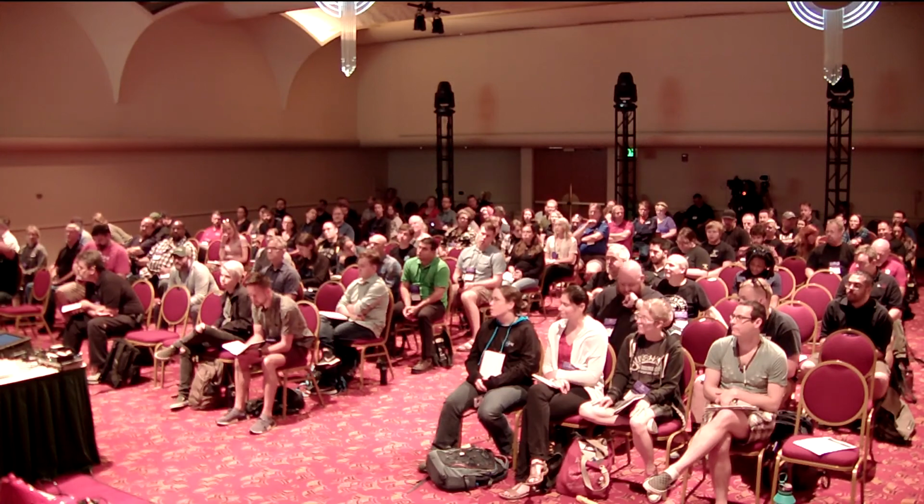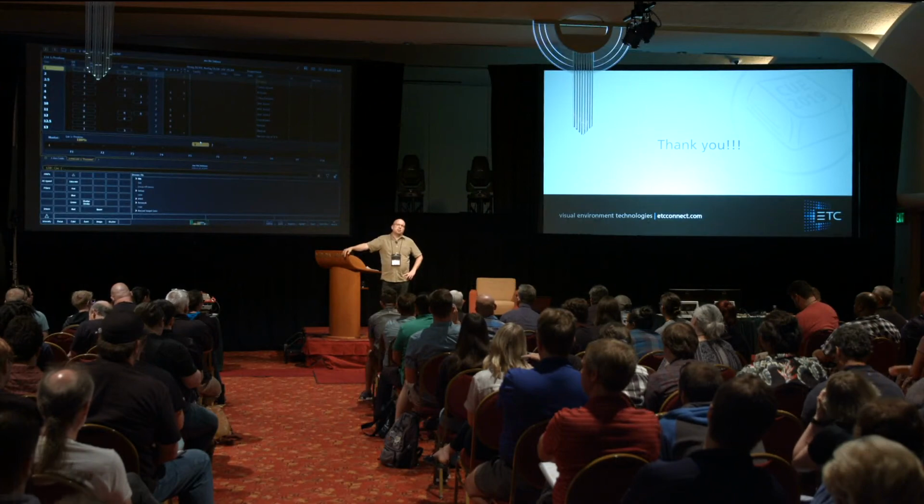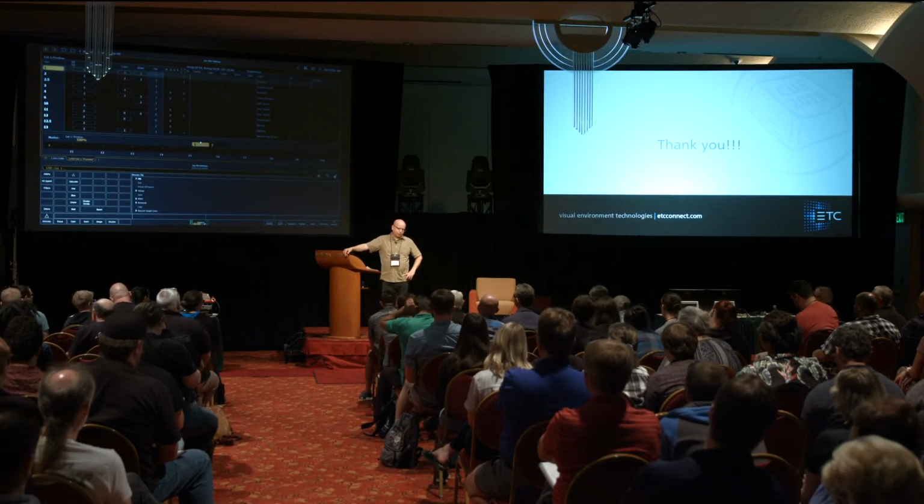Sure. So the question is kind of, what is show control, really? Right. So show control is kind of an umbrella term that we use. So you've got what I would call like live or streaming control. So that's what DMX is. That's what streaming ACN is. It's things that are more or less continuously happening. I want to be able to turn the encoder and my light should pan totally smoothly. So that communication from the control desk to the light is what I call the live or the streaming control. Show control is more things triggering other things, is as broad as I would put it.